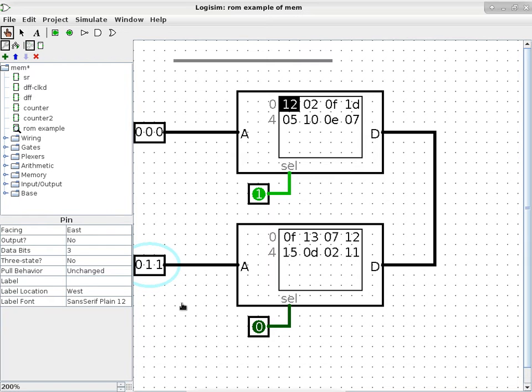Okay, so let's turn on this ROM and say, okay, ROM number 2 or bottom ROM, now pay attention to the address line, and we want you to output as well. Okay, not a problem. The output, which is shared between the two, is 10010. Cool, nothing is problematic. What happens when they disagree, though? Aha! That's exactly what I want to go to. Okay, very good. I like those discussions where you guys are leading me.